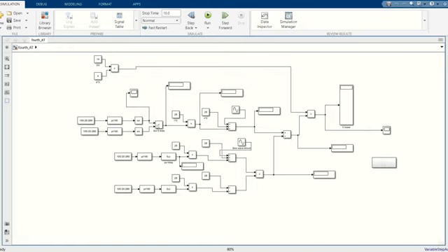We have given it to the product block, that is sine square theta, same as below. We have also attached an individual scope to each, so that we can display the instantaneous output of that system. After that, we have connected sinusoidal wave blocks and a repeating sequence block for V tower. The final product, we have given a scope of V tower.